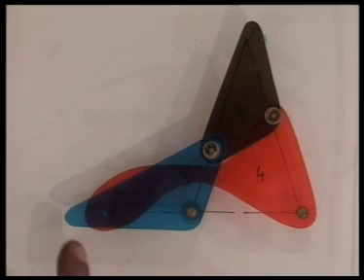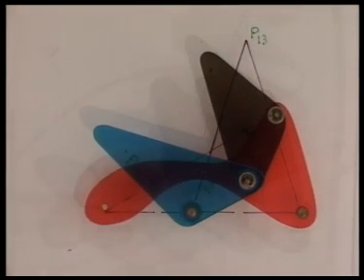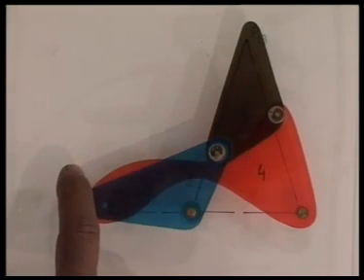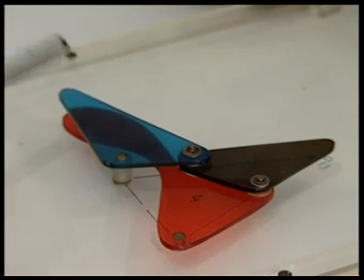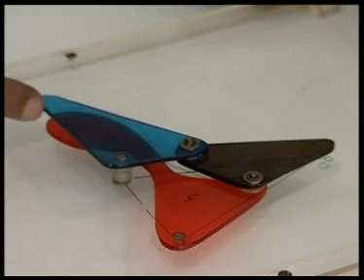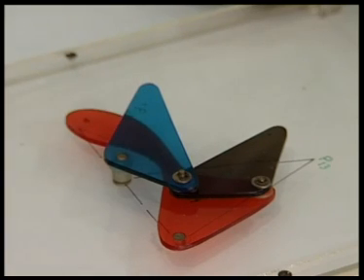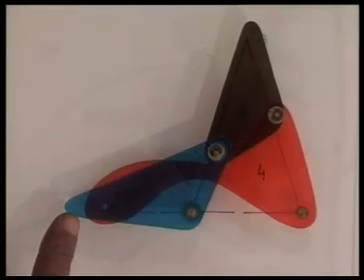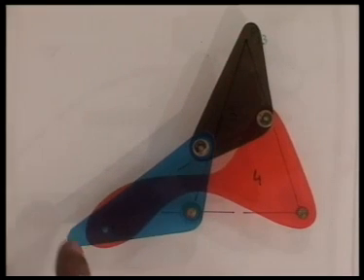And if we move this, you see this is the hole which was coincident with this P24. Right now this is a different configuration, so their location is elsewhere, but at that configuration this hole on link 4 and the point on link 2 you cannot distinguish because they move with same velocity. Here you can see them distinctly. This is the hole which was coincident with this point at this configuration. So around this configuration, these 2 points, one belonging to body 2 and the other belonging to body 4, move with same velocity.